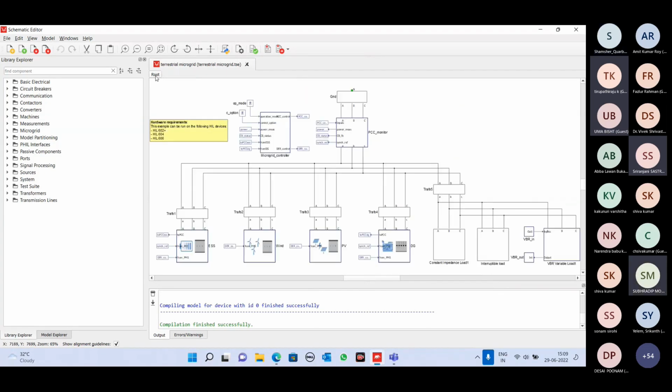And this one is the microgrid central controller. This is the brain of this microgrid. Many conditions are defined from here. Using that, we can connect and disconnect a particular distributed energy resource. Also, we can make a particular distributed energy resource behave like a master, so that the other distributed energy resources will follow it in islanded mode.